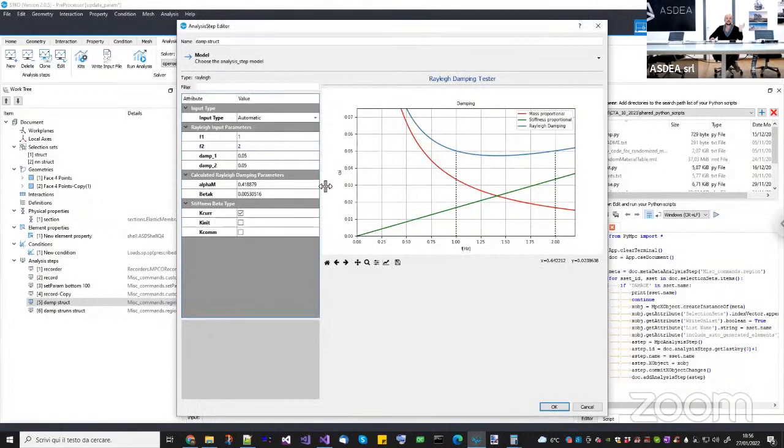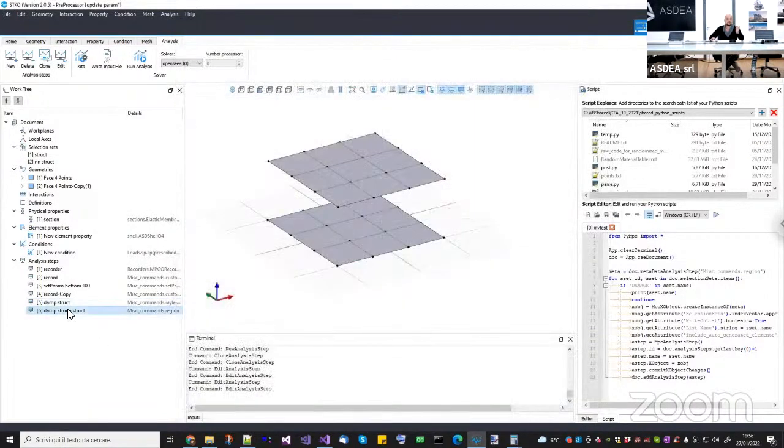Rayleigh damping, which is the damping that you assign to the entire model. Then you create a region command only for a portion of your model whose damping parameters should be different. This is actually the same, because in OpenSees the second command overwrites the first one. So you can do the first one for the entire model and then change some portions. It's exactly the same thing.